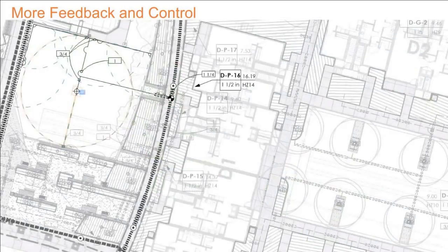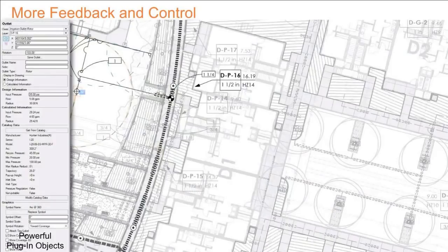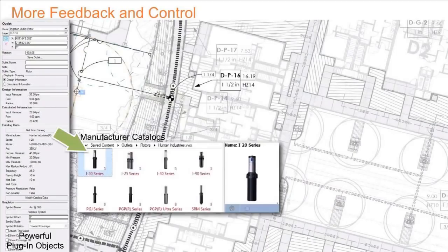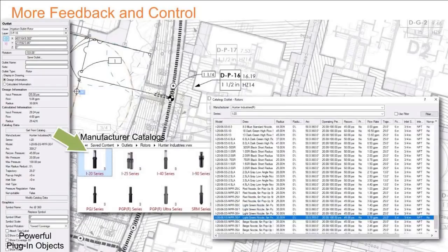Irrigation is one of the big ones that we rely on. Land Effects offers a great irrigation tool. Vectorworks now offers a great irrigation tool as well. And the same idea, having components with this data. So instead of holding onto that paper catalog, that Hunter paper catalog that you may have, this data is embedded. This catalog is embedded in the software. We can pick, in this case, a Hunter i20 head and use it to do our design.